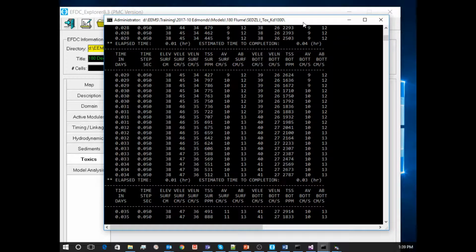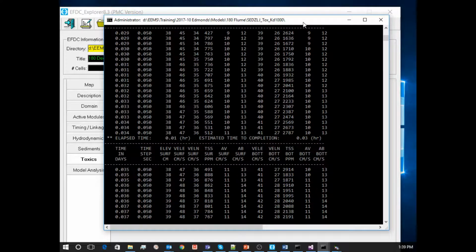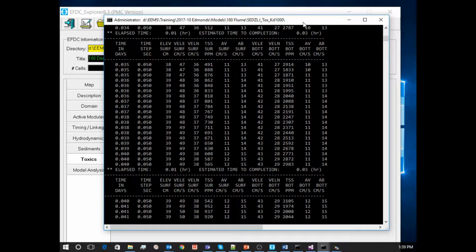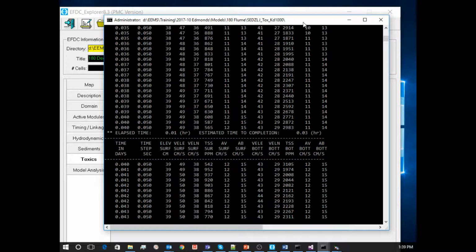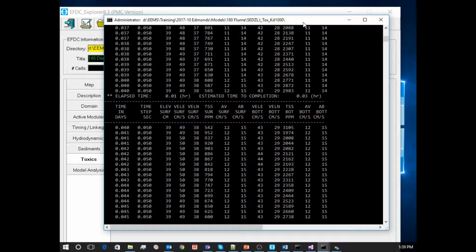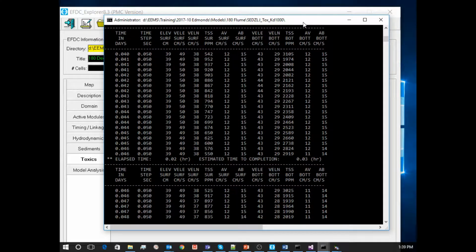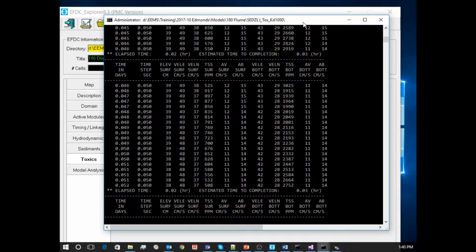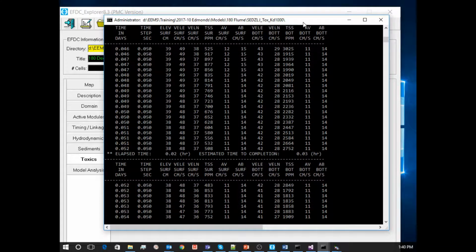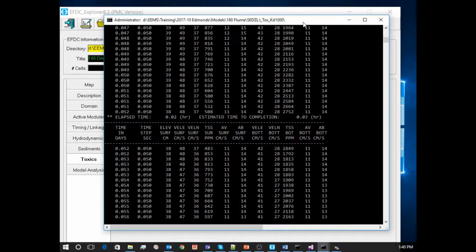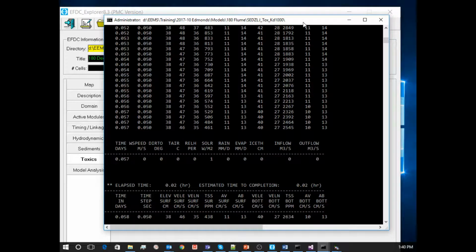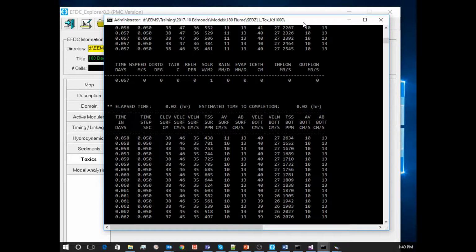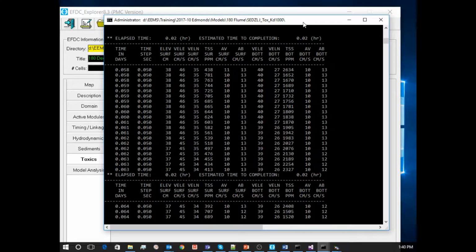And what I want to do is actually kind of look at varying volatilization. Let's look at a few processes that we can adjust for volatilization and see what impact it has on the results. We need to run a mass balance on this so we can show how much mass is being lost, because we should be getting it actually in grams of toxic loss due to the volatilization.